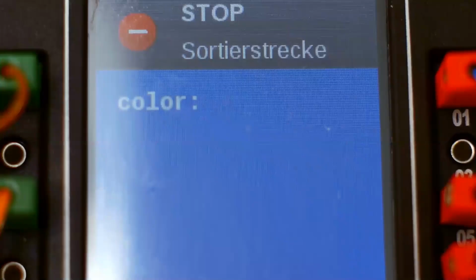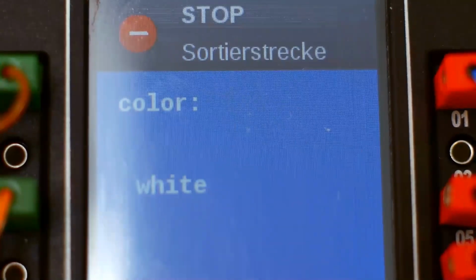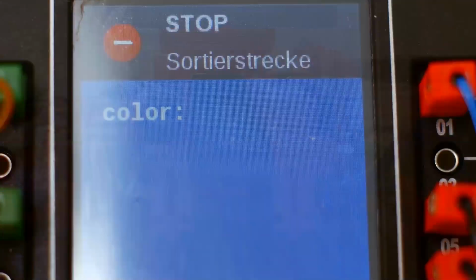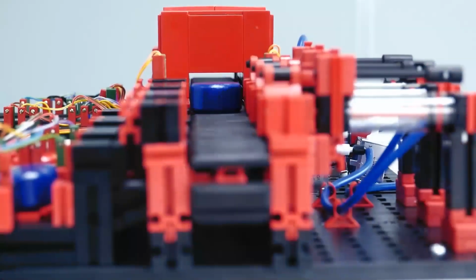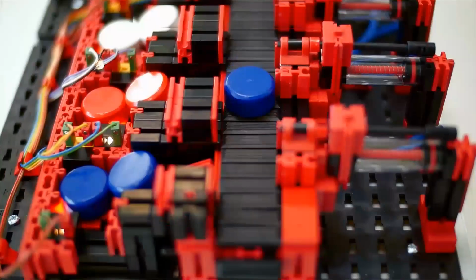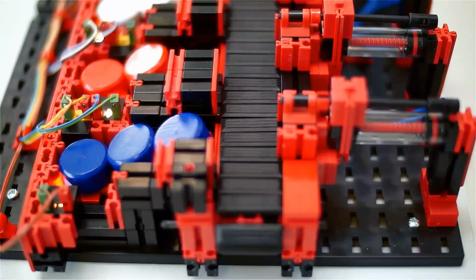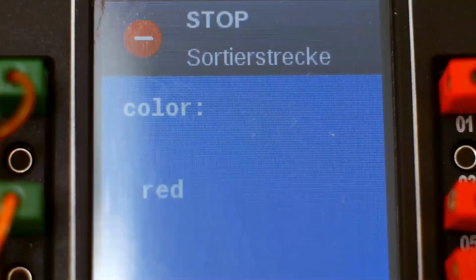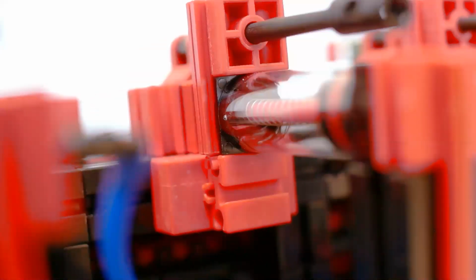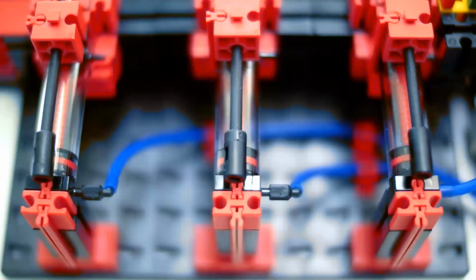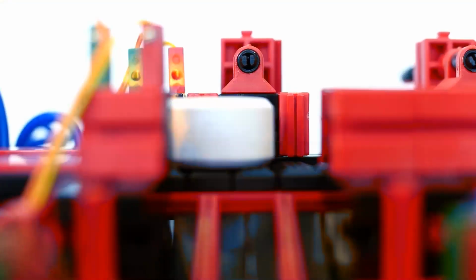The dimensions for this model are approximately 20 by 14 by 12 inches, and it has a weight of about 10 pounds. Now, as with the models we've looked at before, the 24-volt version has a relay board for motor polarity reversal and both a multi-pin connector, again 26 pins with a grid of 2.54 millimeters, as well as additional PCB terminals with push-in connections for all inputs and outputs. And again, you need to provide the PLC and the programming. The 9-volt version, once again, comes pre-wired to a pre-programmed TXT controller, and one 120-volt power adapter is required.